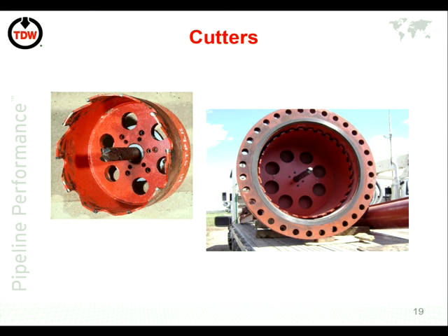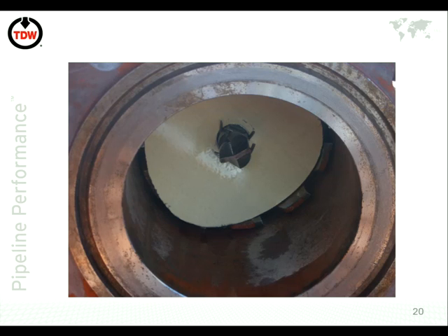Right, so with the drill itself and the cutter, the one thing that will happen is you'll be left with a portion of the pipe, and you have to make sure that that can come out. So the pilot drill we talk about has another function, what are called U-wires on there. As that drill passes into the pipe, the U-wires fall down, and they prevent the piece, the coupon as it's called, from falling into the pipeline, and we can pull that out.